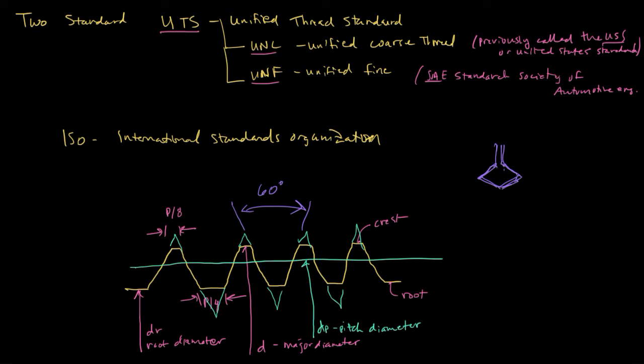The height of the thread, h, is the height of this triangular square wave here, and this height can be calculated as √3 over 2 from geometry of the pitch length. And there's other non-standard thread geometries that are defined, or specialty threads, but these are the most commonly used and probably the most likely that you would use in your machine.